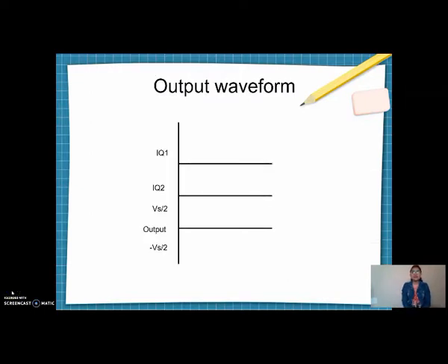This is how the waveform will be at the output. It is quite clear that a steady DC voltage is getting converted into an alternating current. This is how an inverter works basically. Now let us look at the simulation of this in Simulink.